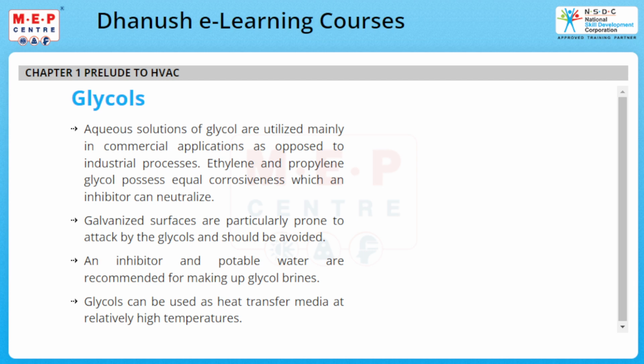Galvanized surfaces are particularly prone to attack by the glycols and should be avoided. An inhibitor and potable water are recommended for making up glycol brines. Glycols can be used as heat transfer media at relatively high temperatures.